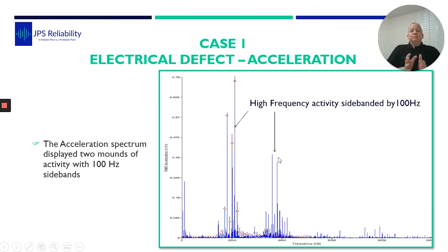And at this point we need to use common sense. While I was there taking the vibration readings, touching, smelling, feeling, yes, the side of the motor was hot. But this is an electrical anomaly. This is a really large motor up on a pedestal. As I clamped the motor, I managed to touch around and feel, and the actual power cable going to the motor was hot to the touch.